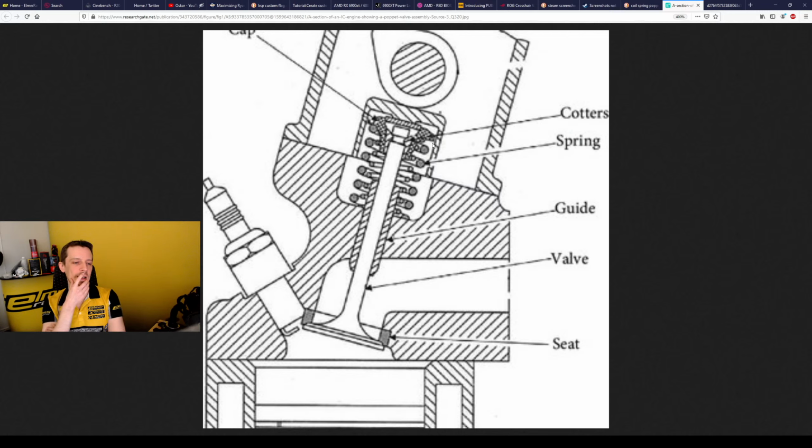I'm not sure how you would close the ends of those, but I guess you could probably invent some way to do that. The manufacturing is definitely going to be the problem with that, so I'm assuming that's why we don't see hollow tube type valve springs instead of solid wire ones. But yeah, you have a single coil, double coil, there are even triple coil spring return things. These are all just for the return section.